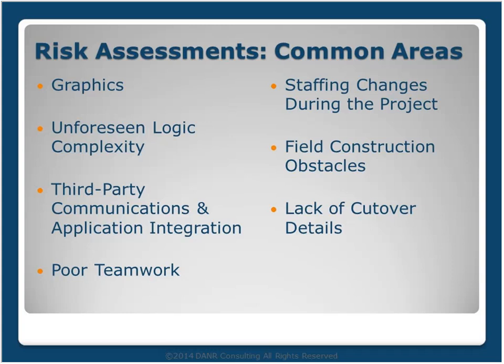And what we discovered was that the site engineers had it in their mind that they could do all of the work hot. And we actually identified some things that they hadn't thought about, and there was no way to do them hot. They were going to have to do a cold cutover of those things. So it actually shifted the entire turnaround schedule for the plant. So thinking about some of those things early on and getting as much detail as you can early on typically helps to address some of these risk areas.